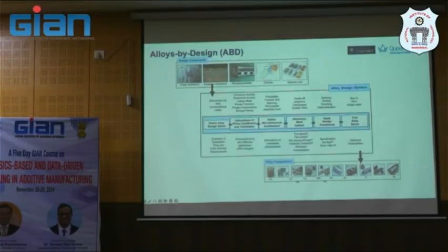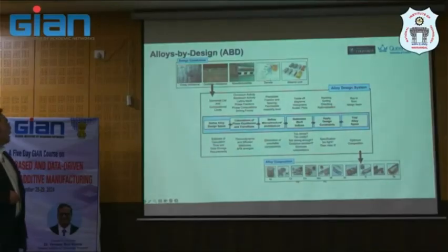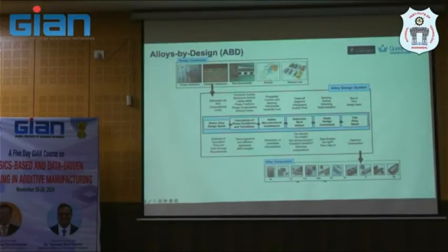In order to calculate this, we need to design the alloy space, calculate phase equilibrium, calculate the microstructure architecture, identify the merit indexes, apply design constraints, and try out some sets of compositions in order to eliminate trial and error.